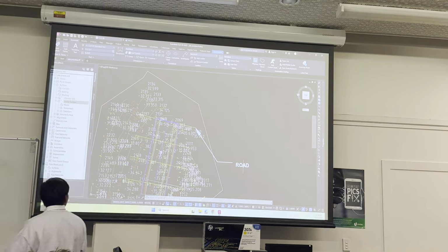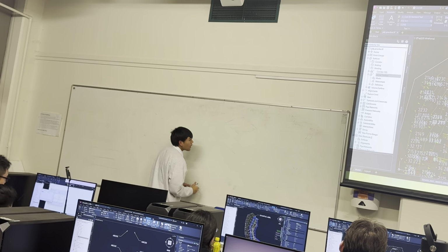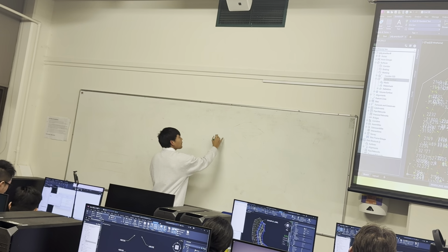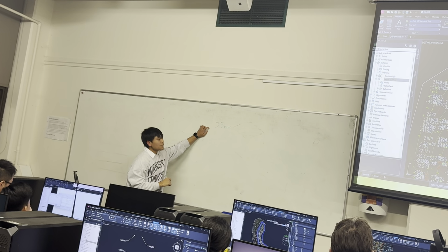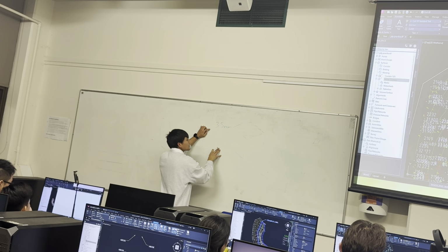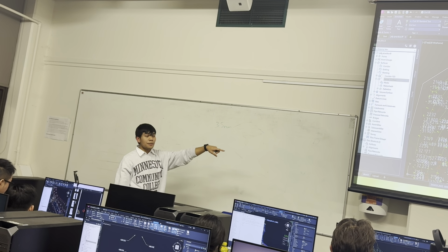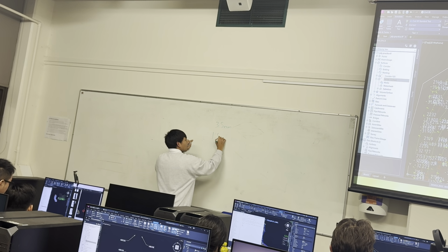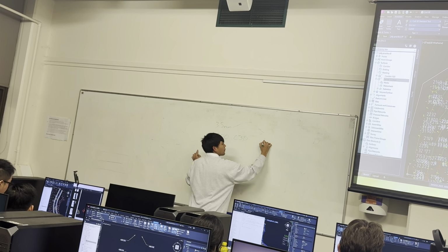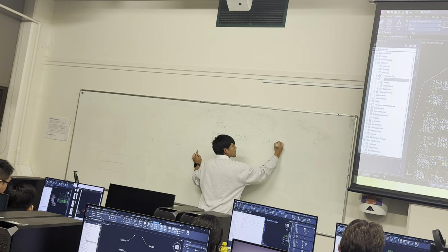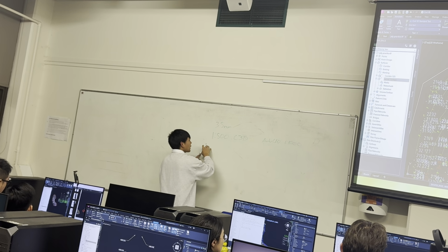For the labeling, for those labels that I just mentioned, just use 3.5 for now, 3.5 millimeters, for your labels. But you'll have to do some calculations, since Civil 3D is by standard 1 to 500, and AutoCAD by standard is 1 to 1000. So we'll have different scales when you export. But I'll tell you guys about that later.